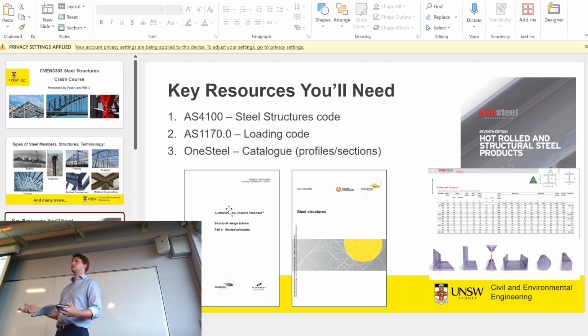You're not. You're going to make that person seem like they're 130 kilos. So you need to increase your loads when you're designing. And in saying that, you also need to make your section capacity less. So you need to act as if the beam that you're using is worse. That code is basically for that. So I'll pass that around.